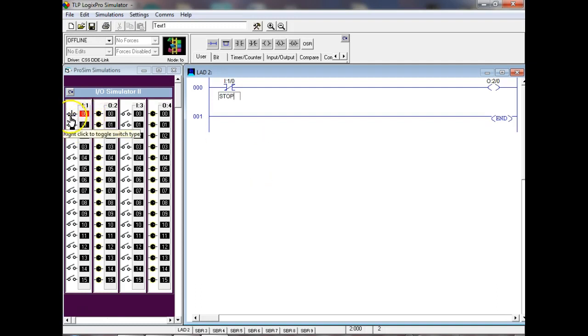Yeah, can you see this? I can't make this any bigger. So now, the problem is, and I forgot what law or OSHA rule it is, a stop button has to be a normally closed push button. These are the buttons that stop motors, right? You understand? Now, why do you want it to be normally closed? So if it breaks, the motor stops. Okay. So this is my stop button over here.